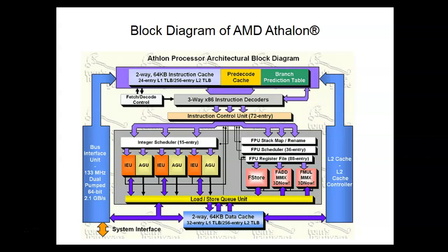Originally, the processor would have one program out there, and as soon as we switched it on, it would go into the ROM memory and look for a binary code that we called an operational code, or an opcode. Then it would go into the instruction decoder, switch to the execute phase, and go out there and do what the opcode told it to do. Every program was just a single-line program.